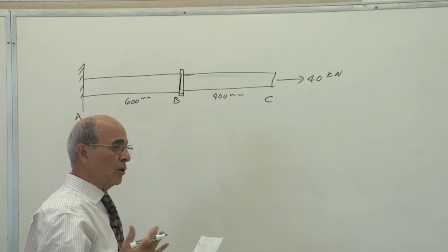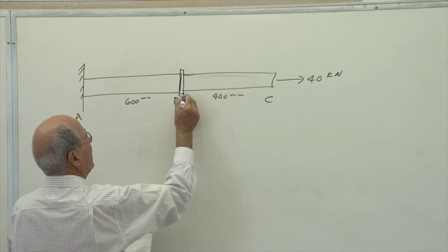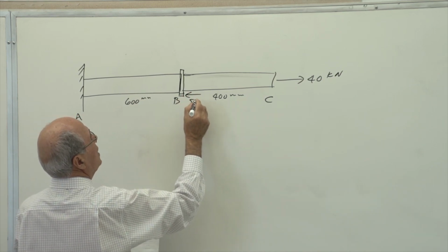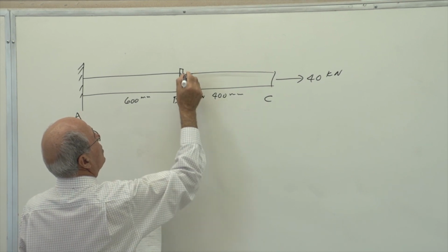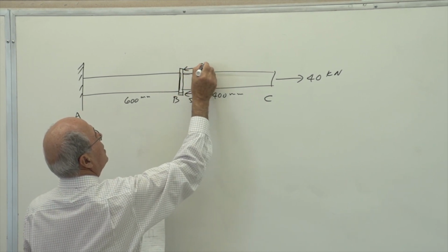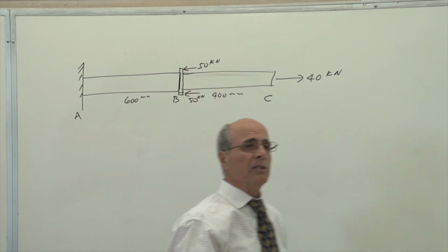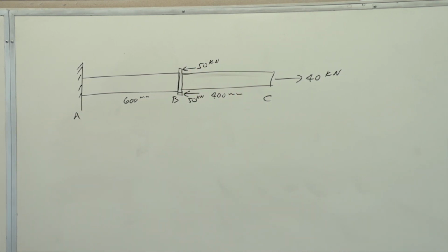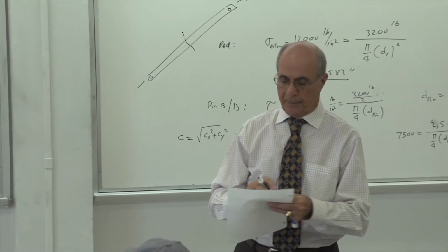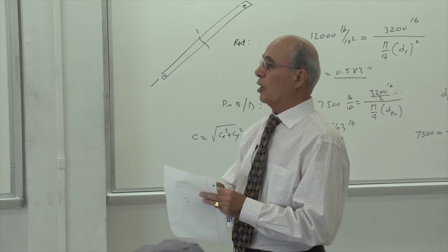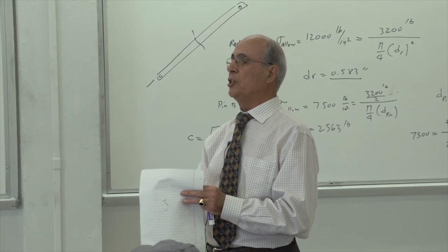We are just putting it there in order to apply a load to it. And here it is 50 kilonewton load and 50 kilonewton later, as if I am applying 100 kilonewton to the center of the rod. That's what is important. Yes? Okay. So therefore, all the loads on this member are axial, we say.